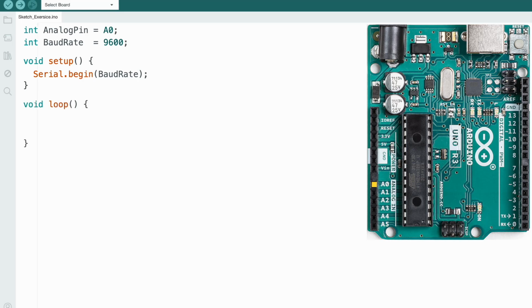From there, we jump into our loop. Now, typically what we see for serial inside of our loop is Serial.println, which prints information into our Arduino IDE. In this case, we're not interested in print statements. We're not interested in visually looking at our IDE and seeing something. We are actually interested in reading a value off the serial line. And so we're going to be reading that value in our Processing IDE, which means from our Arduino board, we need to write to the serial line.